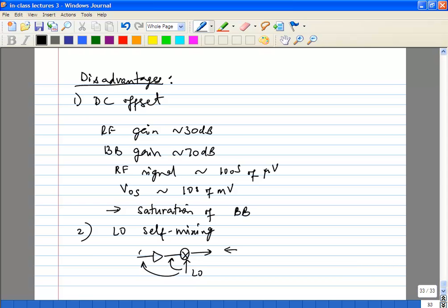So what do you have here? You again have DC offsets from your LO leakage. And remember, let me just put the antenna here. We talked about re-radiation from the antenna. What can happen is, if you have some kind of reflection and it comes back and gets received again, you can have time varying DC offsets depending on the reflection paths.